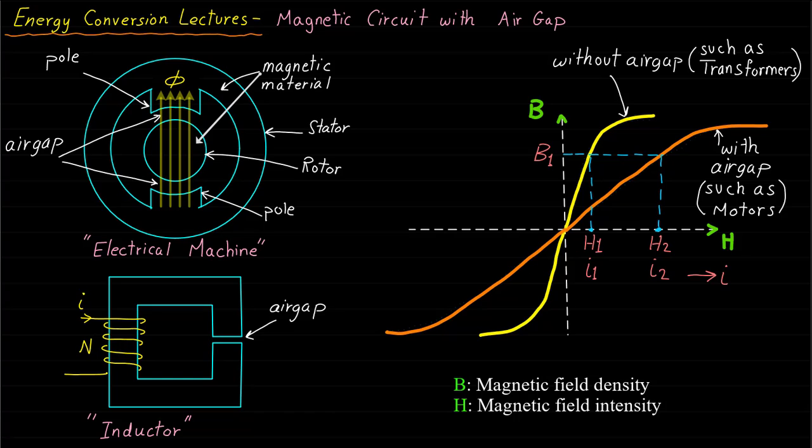Basically, if you have a magnetic circuit and you need to apply high current or store high energy without the risk of saturation, you need to add an air gap to your design of the magnetic circuit. It should be noted here that abnormal operating conditions can also lead to saturation and cause damage to the magnetic circuits. Therefore, an air gap can also be implemented to protect the magnetic circuits from saturation and abnormal conditions.